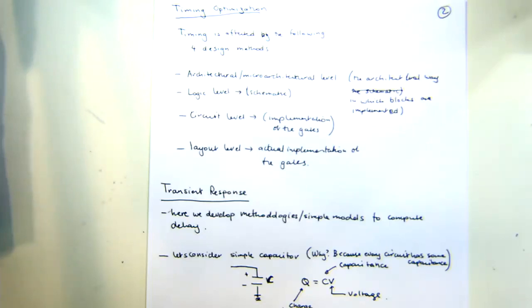And usually, for all of you that are passionate about FPGA design, your colleague who wasn't here that was wanting to do FPGA design when he went back home, if you were doing that in an FPGA, you wouldn't actually use the multiplication symbol. What you would do is you would instantiate a multiplier from Xilinx or Altera. I think Altera is Intel now. So from the Intel library, which implemented a multiplier, which would probably be 100, if not 1,000 times faster.